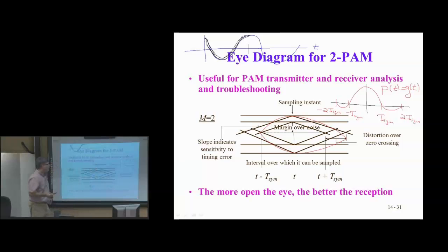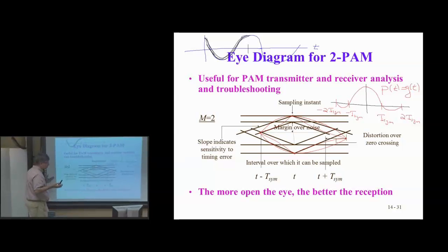And if there's no noise and there's no sampling mismatch between receiver and transmitter, you get a very clean eye. Now, you also get the tails of the sinc. They're going to add to the next period, so you'll get a little bit of contribution from those tails. Okay. And if there's no noise, you get a diagram that looks like this. And this looks like a human eye.